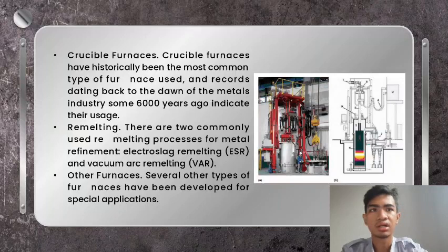An electric arc is established between the electrode and the melt pool in the crucible, which gradually melts droplets from the electrode into the crucible. When an adequate melt quantity has been obtained, the residual electrode is quickly retracted and the crucible is tilted for pouring into molds. Vacuum skull melting was once the dominant method used for melting titanium, but VAR furnaces with static crucibles are used in titanium primary melting today.